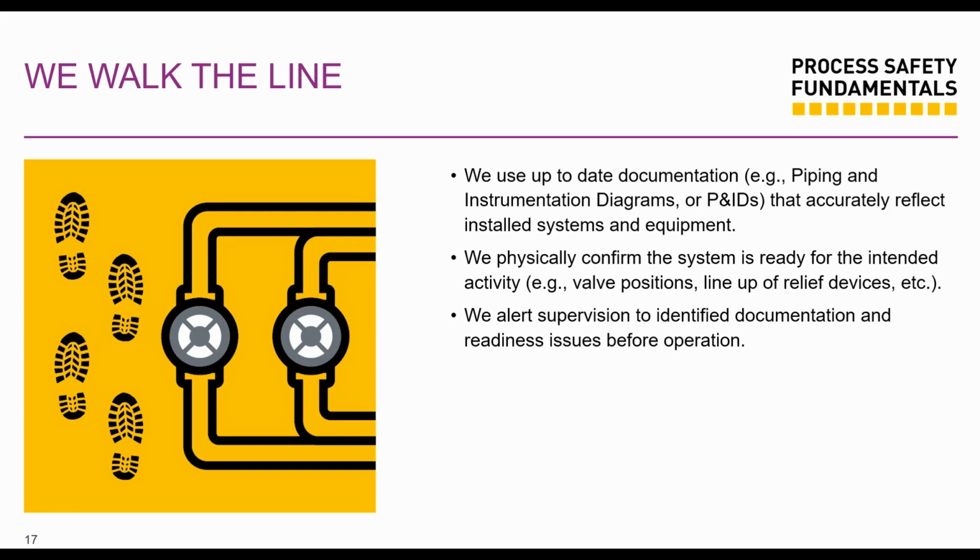You're lining up your pumps, and you find out a bypass valve was left open. During your walk the line, you could actually catch it. Or you do a turnaround and you start up a unit without a walk the line after your turnaround, and then a temporary blind flange is missing, or a spectacle blind was removed from that drain line, and then you have your leak from that line, and then you have a fire.